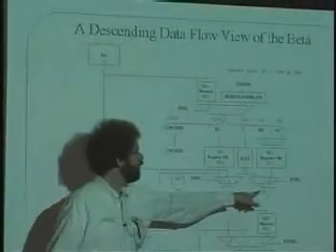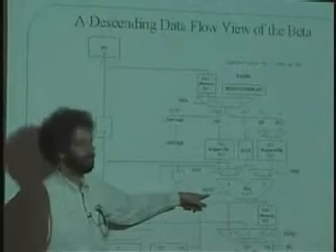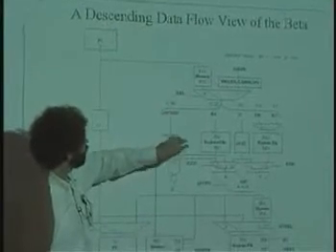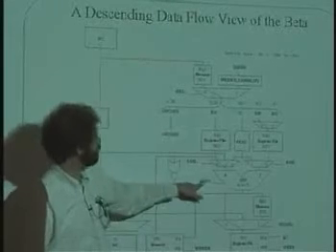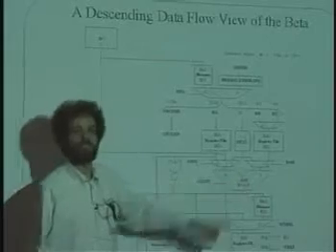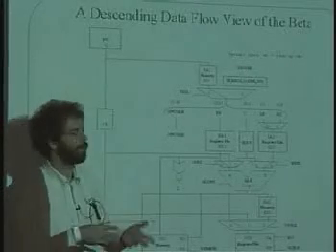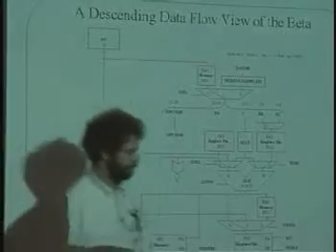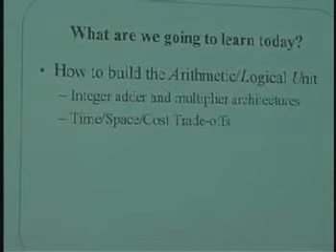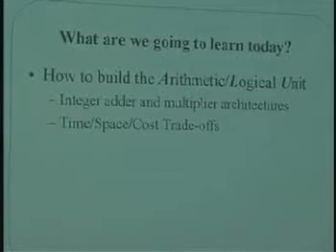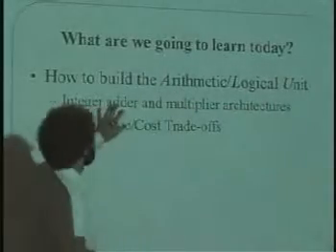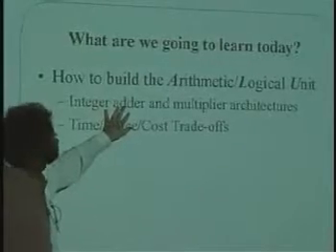It takes the A and the B and takes some sort of an opcode from the instruction stream that is decoded. In other words, there's going to be some logic between this opcode and the command to the ALU saying what function to do, and the ALU is actually going to do the work, and it's going to do things like adding and subtracting, and, or, XOR, stuff like that. Now, we need to think about a couple of different things. First of all, there are things in order to add. How do we add numbers?